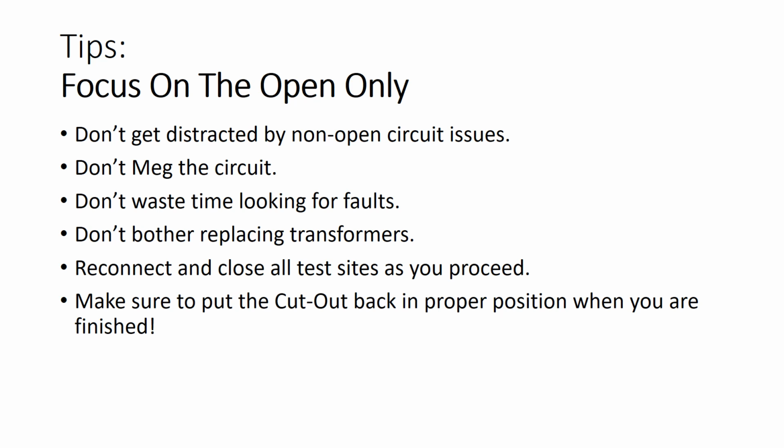Make sure you reconnect and close all test sites as you proceed. That's very important. If you're creating more opens as you go along, it's going to get more and more confusing. And finally, when you're done, make sure to put the S1 cutout back in its proper position when you're finished. Otherwise, the next guy that comes along is going to have a problem.